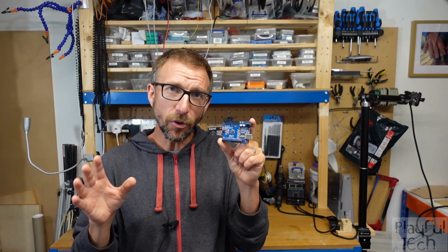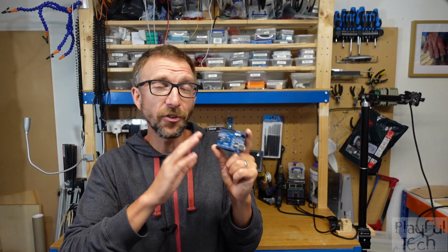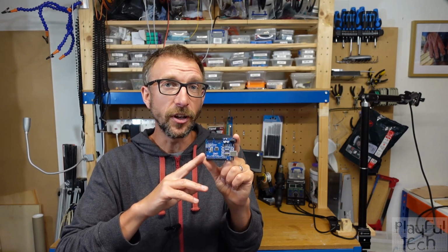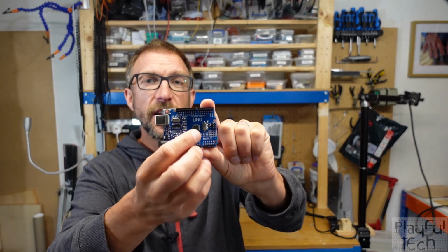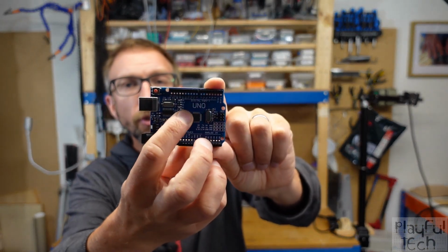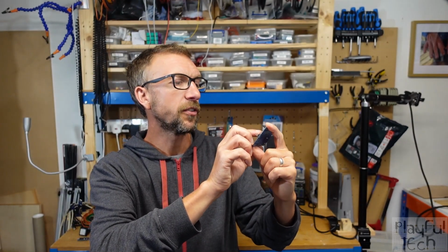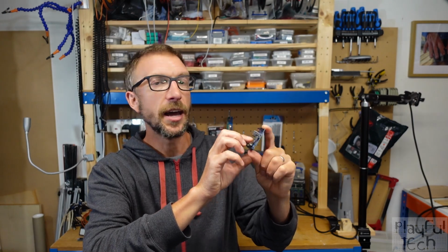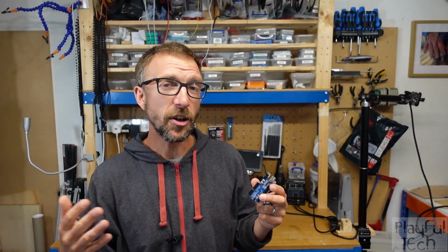Now, PWM control generally requires the use of a particular timer hardware on the processor, so not every GPIO pin supports it. On an Arduino Uno, you can tell which pins they are because they're the pins with these little squiggles on them. So they're pins 3, 5, 6, 9, 10 and 11. So there's 6 pins on Arduino Uno. On an ESP8266, I believe any GPIO pin can be used to support PWM output.